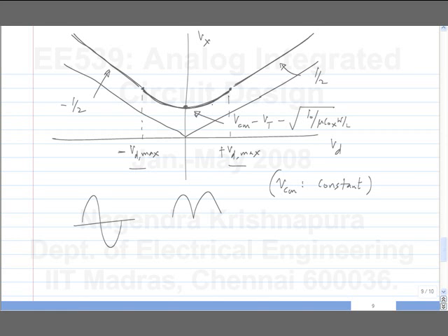Only thing is, if you have very small voltages, the slope is 0. You will not see any change at all. For large voltages, it behaves like a rectifier. In general, even functions are useful to detect the strength of signals. If you think of the definition of RMS signal, it has something to do with the square of the signal, right? So in general, the square or the even function is involved when you want to detect the strength of the signal.